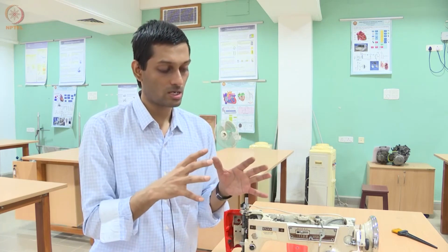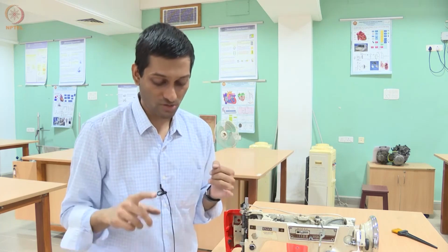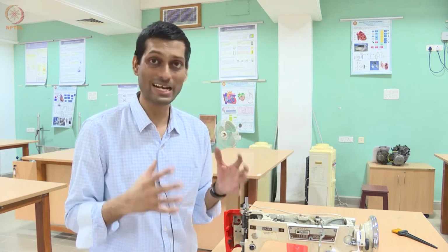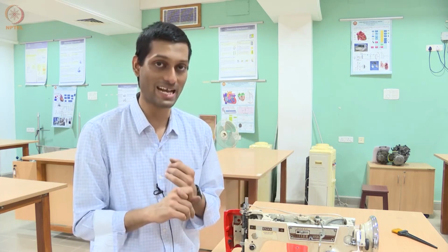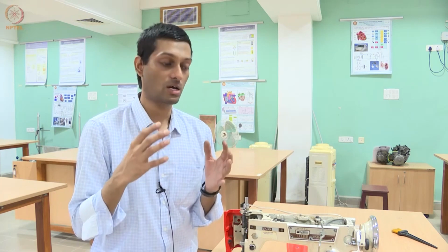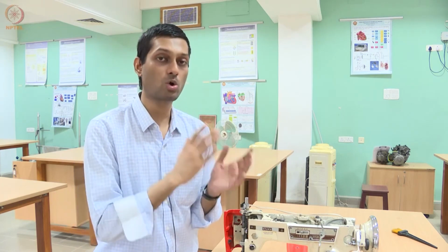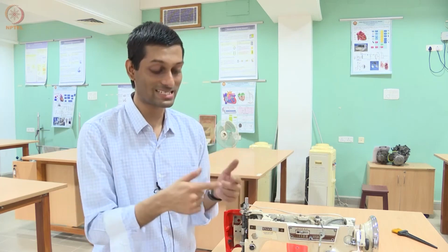What are the other things we learned today? We learned about tension regulation, the importance of tension regulation, the importance of synchronizing the movements of different mechanisms, and the way to convert a rotary motion into a reciprocating or an oscillatory motion. How do you convert rotary motion into a reciprocating motion? A crank slider or a crank rocker, right? Rotary to oscillatory, you use a crank rocker. Rotary to reciprocating, you use a crank slider, right?